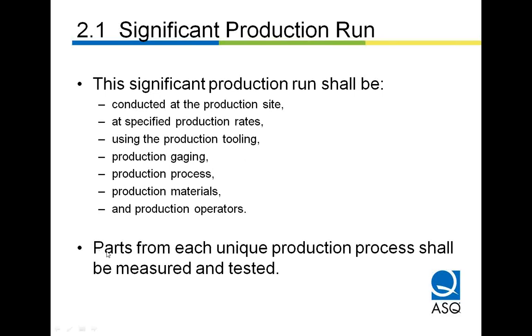There's also a note here that parts from each unique production process have to be measured and tested. We want to be sure that if we have a four cavity mold, parts from each of the four cavities are conforming, are consistent, and that they're not different from each other.